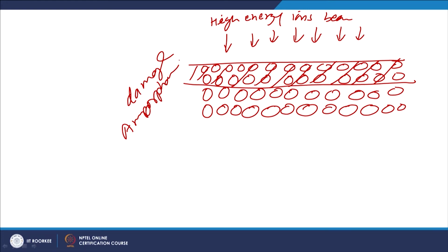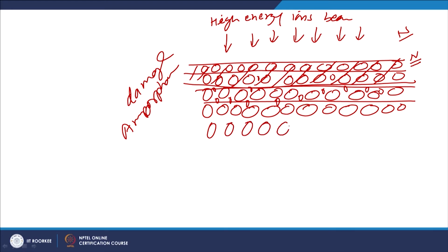At the same time, these ions of a particular element like nitrogen, when they get introduced in the metal, will be interacting with the substrate material to form their respective compounds. So now we will see in this situation that obviously the concentration of that particular element will be more near the surface layers, and that concentration will keep on decreasing, and far at a significant depth from the surface there won't be any change in the crystal structure as well as any change in the